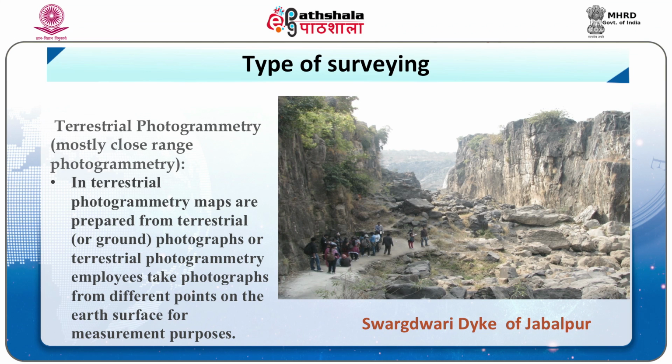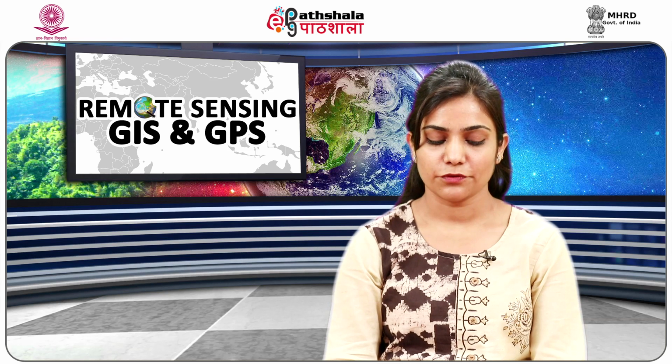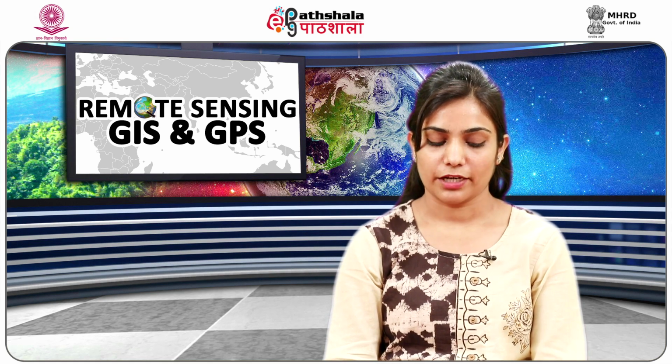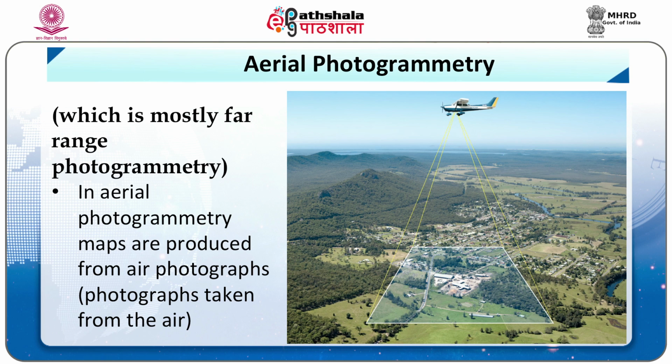Terrestrial or ground photogrammetry. In terrestrial photogrammetry, maps are prepared from terrestrial or ground photographs. In terrestrial photogrammetry, we take photographs from different points on the earth's surface for measurement purposes. This is mostly close range photogrammetry. The terrestrial photogrammetric survey is considered a further development of plane table surveying. Next is aerial photogrammetry. In aerial photogrammetry, maps are produced from aerial photographs taken from the air. This is mostly far range photogrammetry.